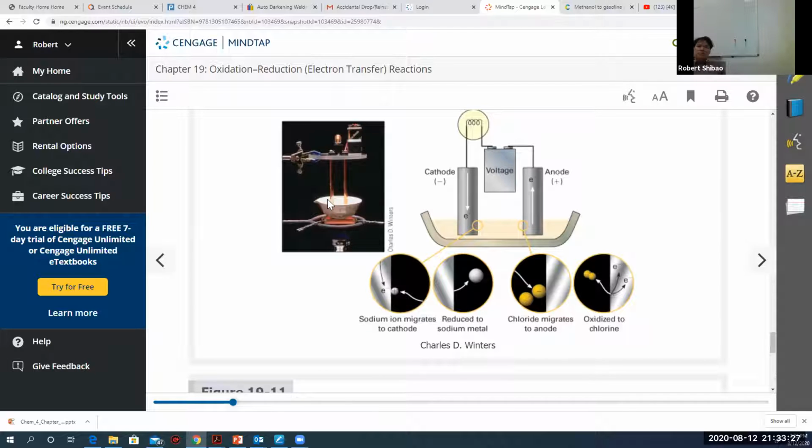This ceramic is usually aluminum oxide, but aluminum oxide is difficult to work. And so this is aluminum oxide mixed with various other cations to make it easier to shape and do that kind of stuff. But it makes it more reactive. If you have just pure aluminum oxide, then it's very unreactive because aluminum oxide is quite a stable lattice. It's like sapphire. Sapphire is just pure aluminum oxide. So I had sapphire crucibles, I had sapphire beakers, a whole bunch of stuff made out of solid sapphire. And it's expensive. And so you just get a porcelain one like this, which is a lot cheaper.